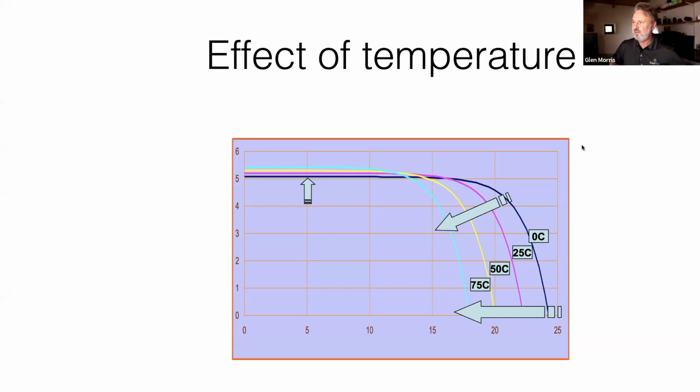Bill's saying, if someone hosed a panel to help reduce temperature, what risk is there of cracking the glass? Well, solar panels are pretty damn tough, actually, Bill. You probably know this yourself. You'd have to be hitting those panels to a tremendous temperature, well beyond their warranted, generally 70, 80 degree warranty, or more than that even, to get the glass sensitive enough to crack. So I don't think it's a problem. I've never experienced it myself, and I've abused a lot of solar panels in many ways. They're surprisingly tough, by the way, like hail tests, etc., that they have to meet.